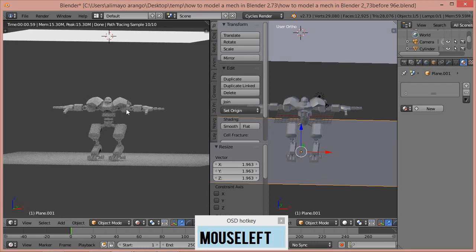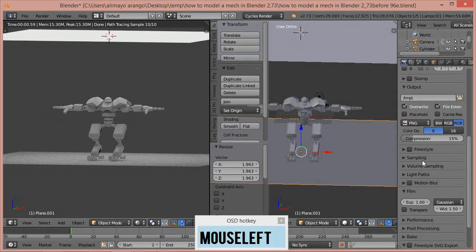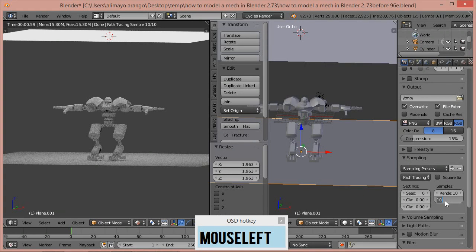If you look here and it looks kind of grainy, it's because of the sampling I have it set at now. The higher your samples, the better and clearer your image tends to look. The samples are only at 10 right now, which is very low, as a matter of fact. Even now, turn the samples up to 100. You can see when you raise the samples, Blender automatically, as soon as you change the setting, increases the clearness and raises the samples up to where you set it.